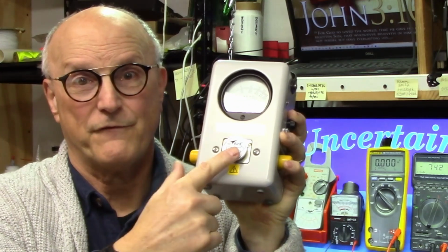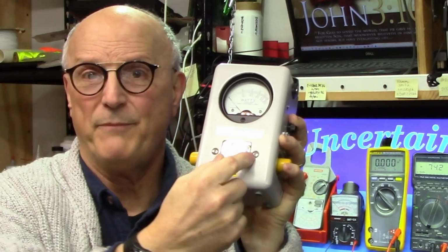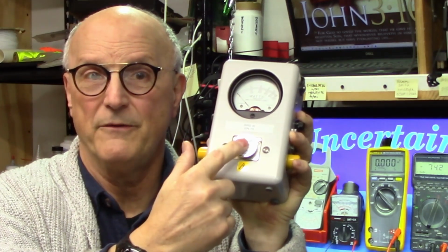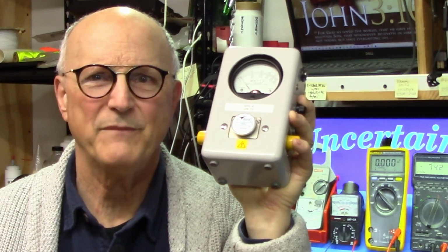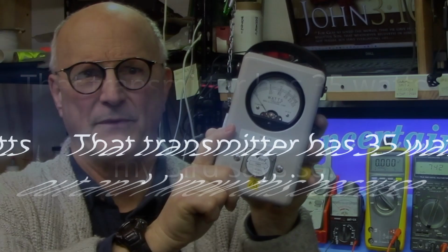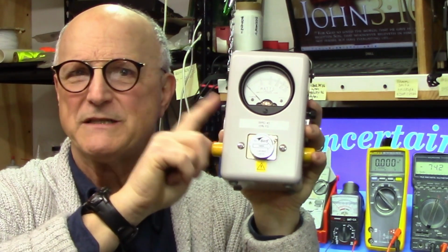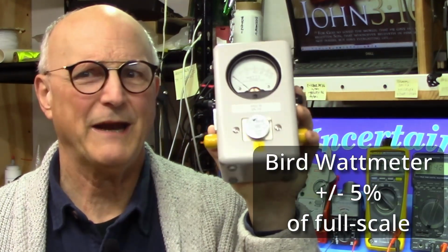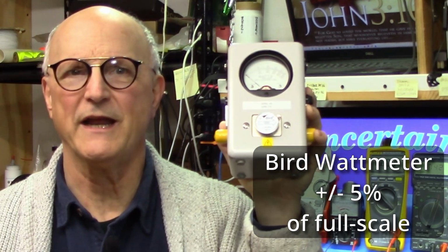Now, you change the frequency range and the full-scale power reading by purchasing different elements which plug into the front of the meter. We use this wonderful and trusted watt meter and say things like, that transmitter has 35 watts out, and I know this because my Bird says so. But if we look at the specifications for this watt meter, we discover that it is rated at plus or minus 5% of its full-scale reading.